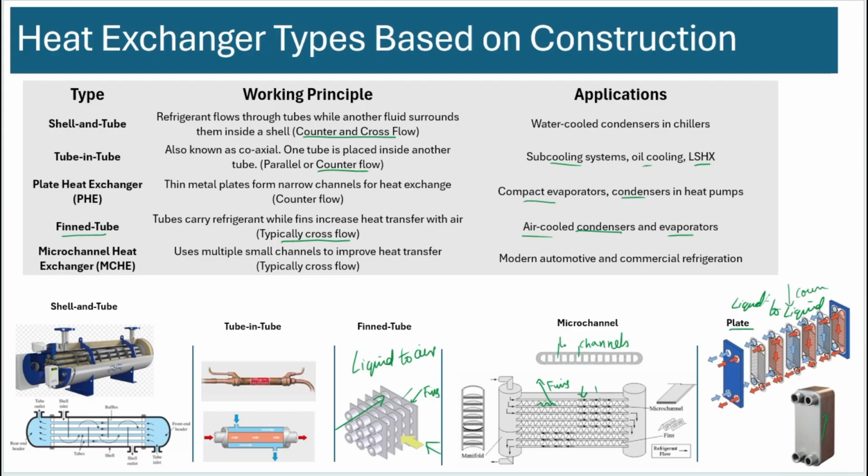So the liquid flows in these channels, okay? And the air flows through these fins. So this is also a cross flow, okay? Because the refrigerant is flowing in one direction from left to right, and the air is going normal to this paper. So it's cross flow. And it's commonly used in automotive, so in your car, and also in commercial refrigeration.